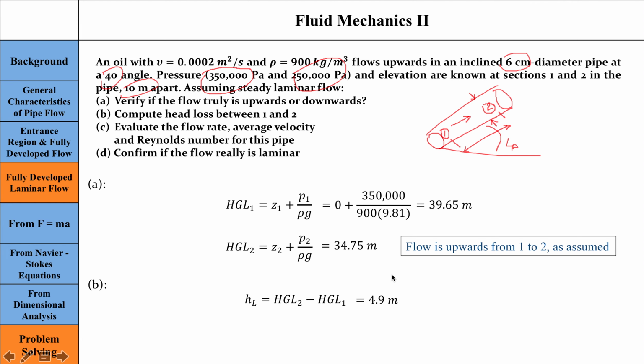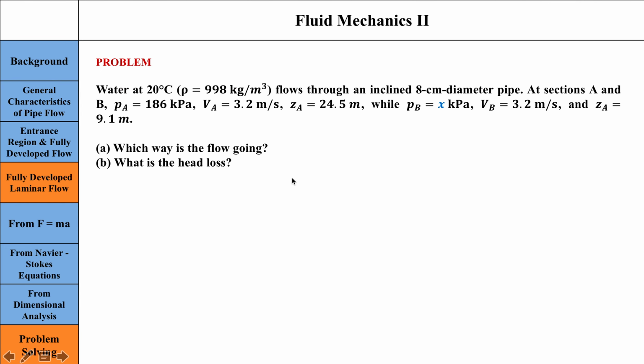So do you understand how, instead of having to use the wall shear stress term, we are just using the HGL, the hydraulic grade line, and it makes our life so much easier? Now I'll leave part C and part D up to you. You can do that yourself. And I'm going to leave this problem for you as well so you can get some practice in.